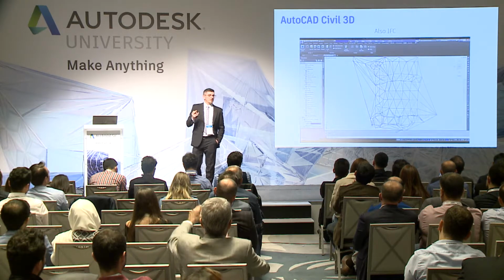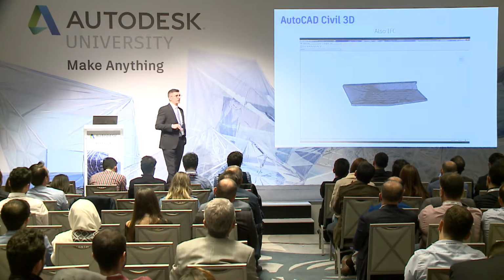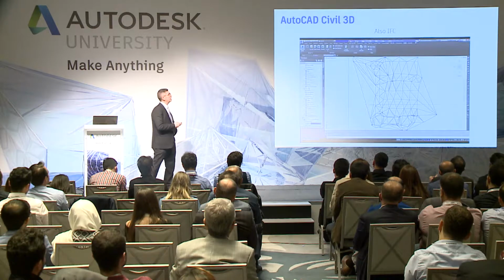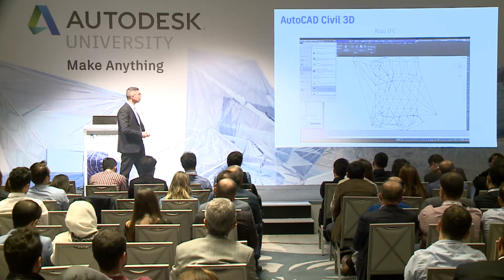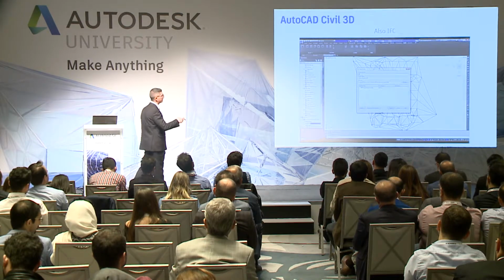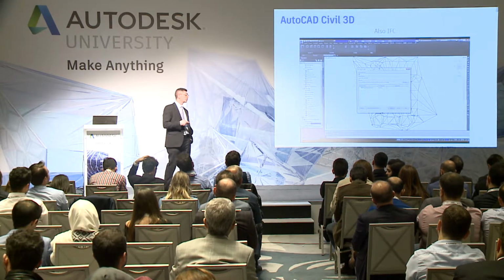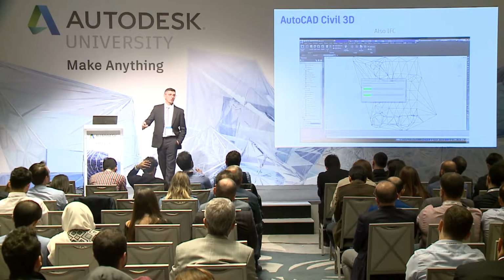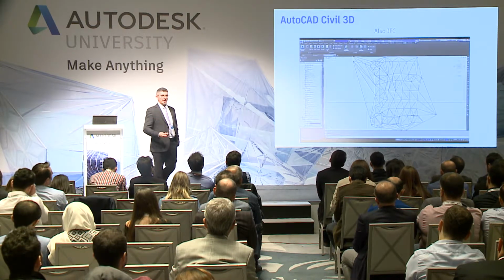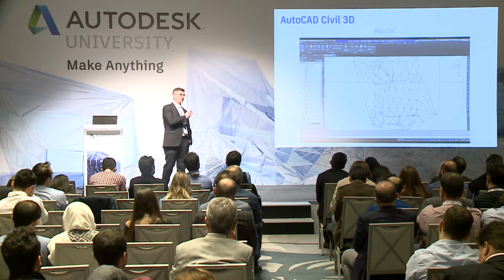Remember, please, that from Civil 3D, we can also manage an export in IFC file. This is a standard file for OpenBIM. There is a tab where it's possible to export, and we can also use this one maybe for Navisworks, or we share it with other people who don't have this type of solution.